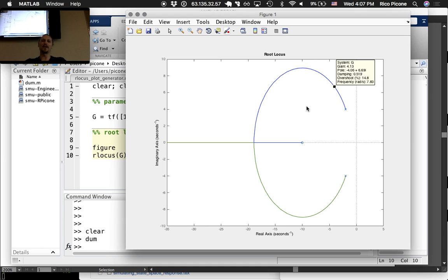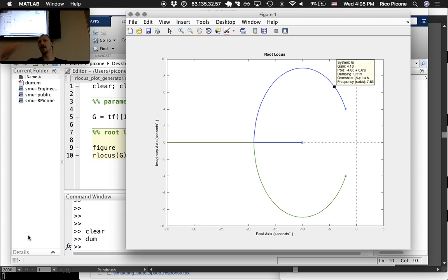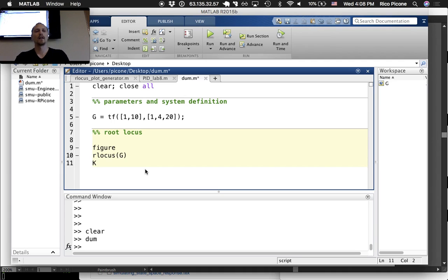This is based on the second order. So this formula that I wrote down, this is the second order approximation assumption. And that is analytically just found assuming that we are not going to have any zeros in the second order. So that assumption, we are going to have a zero, so it isn't completely true. It's going to be approximate. So let's just choose a gain of 4.13 and go from there. So we'll say our design gain, KP, is 4.13.